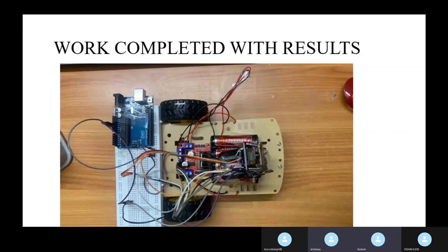Now on top of the batteries, we have placed the ESP32 that also holds the camera. This ESP32 is connected to a stand that is connected to a servo. So this way the angle of the camera can be changed, and using that, we can get various views from the robot's camera.